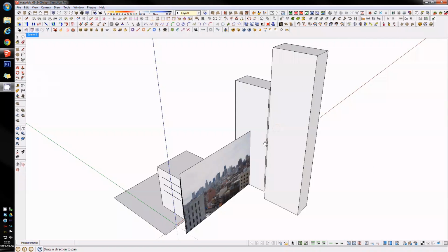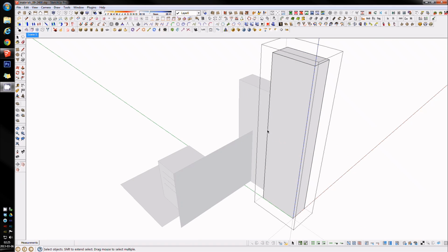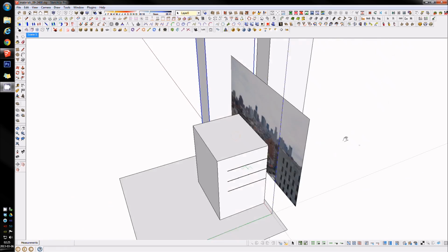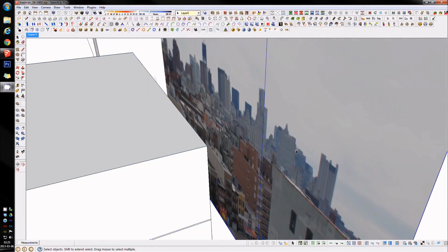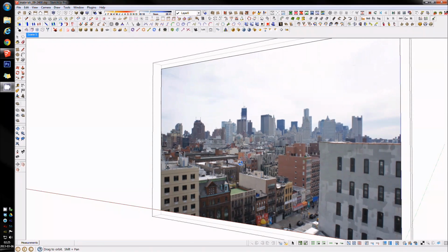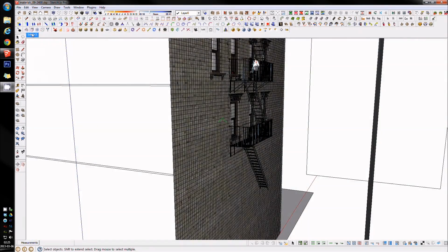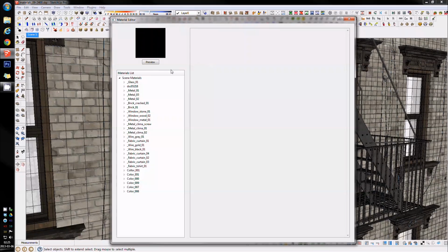To illuminate this scene, I used V-Ray Sun with pretty basic settings. To simulate shadows on the elevation, I used two high boxes at enough distance to achieve some blue shadows without changing settings in V-Ray for SketchUp. However, the reflections in the windows are made from a projected photo, which is in front of the model. When everything was modeled, it was time for texturing.